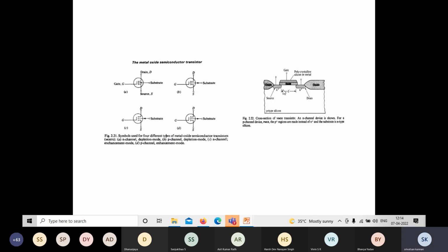So you can see the oxide coating, and this acts as an insulator between these two conductors. So it acts as a capacitor. So when you connect this positive supply on the gate, this becomes positive charge carriers, and here we have negative charge carriers. So negative charge carriers, what will happen?